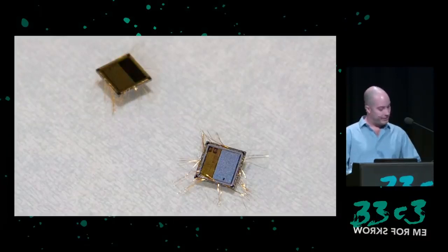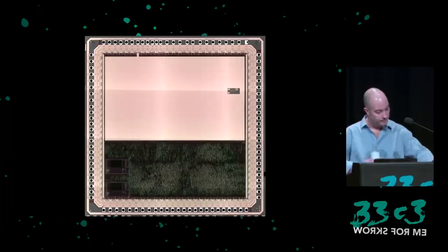After the decapsulation, the bare chips are left with bonding wires attached to them, so these wires will be plucked off using tweezers to get them out of the way. Already in this photo, we can see some of the larger structures on the chip. Half of it is covered with a metal plane, and the other half shows some kind of visible circuitry.